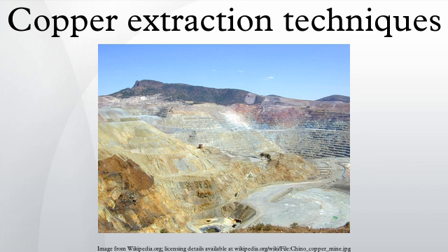The amount of copper lost as oxide copper increases as the oxygen potential of the slag increases. The oxygen potential generally increases as the copper content of the matte is increased. Thus the loss of copper as oxide increases as the copper content of the matte increases. On the other hand, the solubility of sulfidic copper in slag decreases as the copper content of the matte increases beyond about 40%. Nagamori calculated that more than half the copper dissolved in slags from mattes containing less than 50% copper is sulfidic copper. Above this figure, oxidic copper begins to dominate.